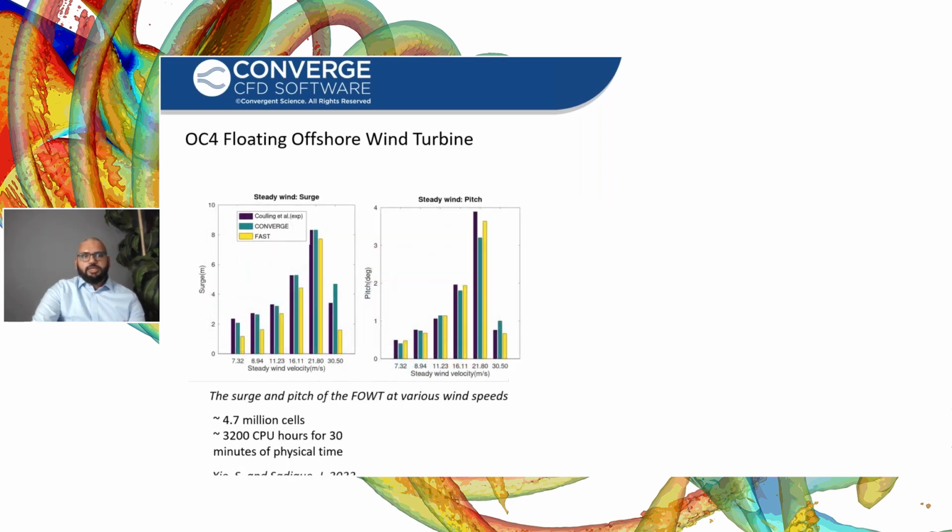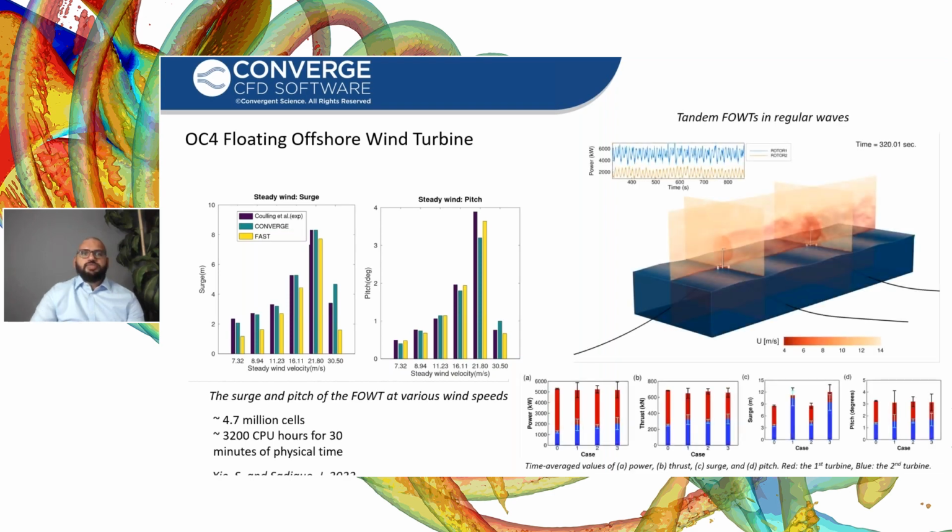So we are able to get a good match for the surge and the pitch for a variety of operating conditions. And we have gone even further. So in the future, what we will have is that we need to be able to simulate offshore wind farms. So in those cases, the interaction between the wakes of turbines become important.